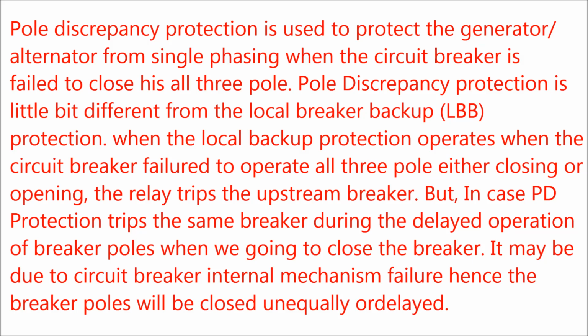But in case PD protection trips the same breaker during a predefined time, it may be due to circuit breaker internal mechanism failure. Hence, the breaker poles will be closed unequally or delayed.